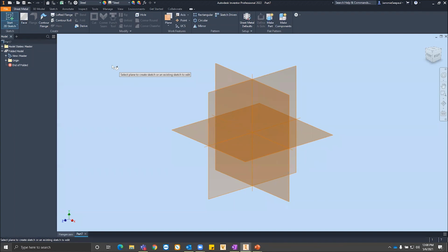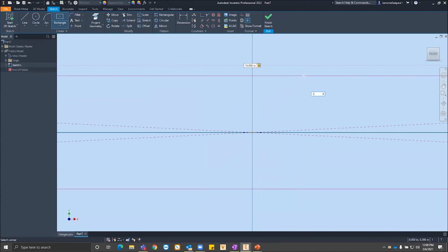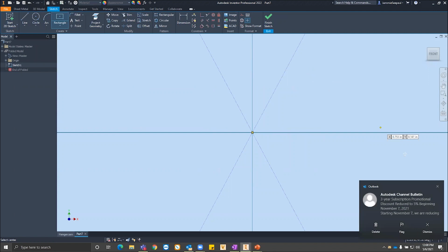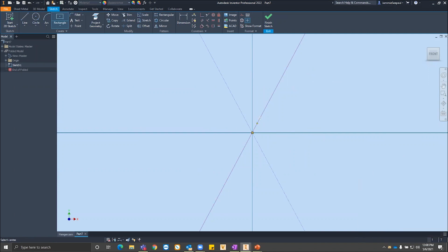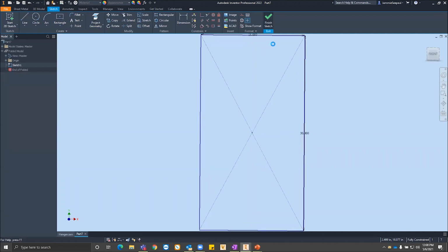All right, so I'm going to create a sketch here for a part. It's going to be a rectangle, so I'm just going to put it here on the XY plane. And we'll put a rectangle here. Good little tip: whenever you create a rectangle in Inventor, it pops up these boxes so you can type the dimension right in. This is going to be a 16, and then I'll hit tab and by 30. It saves you a step in having to go out and dimension the rest of this box. It's fully constrained now, so it's kind of a one-step deal. So I'll finish the sketch.